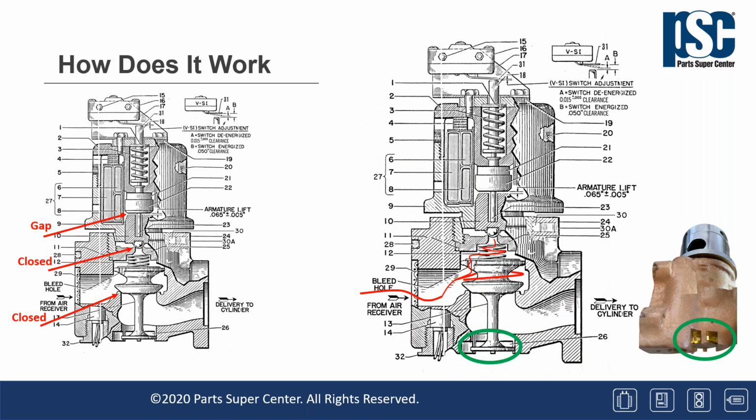An auxiliary switch contact or the mechanism operated contact has interrupted the current now for the cutoff winding VCO, now that the circuit breaker is closed and latched. So the piston in the control valve is now in the closed position, shutting off the flow of air through the valve and opening the exhaust port at the bottom of the valve.